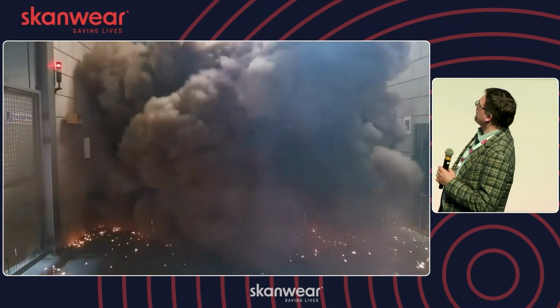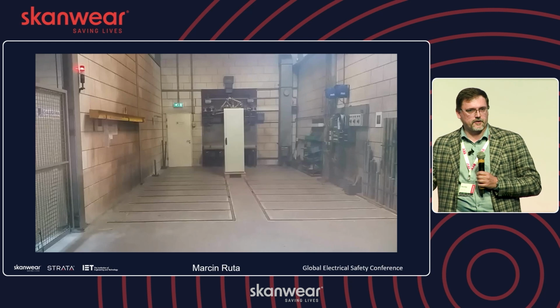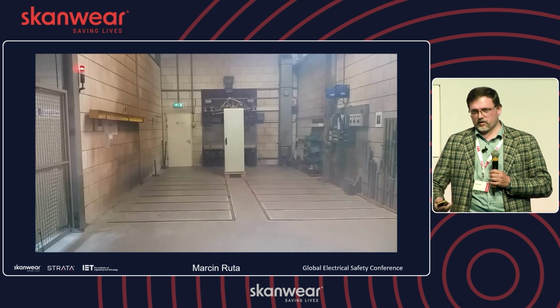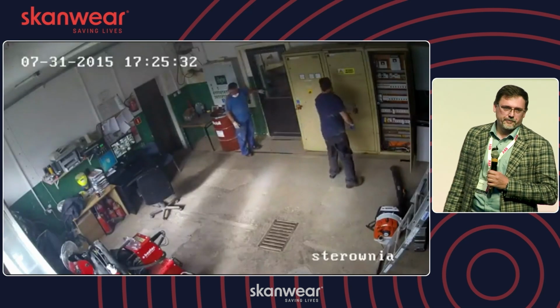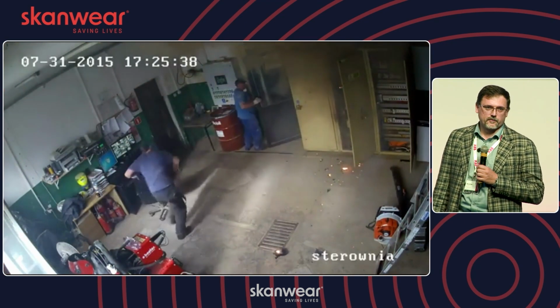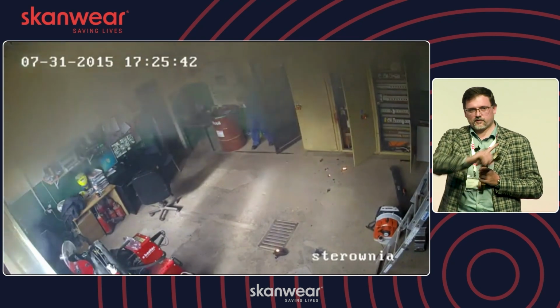When it talks about the arc flash, this was a 25,000 amps half-second test only, which is something around 16 to 20 calories per square centimeter, just to give you a reference. But it can also end up like a recording where you can see something like this. A very minor accident. Actually, it would sometimes be hard to call it an accident at some point. There is a bonus if you look at this side.